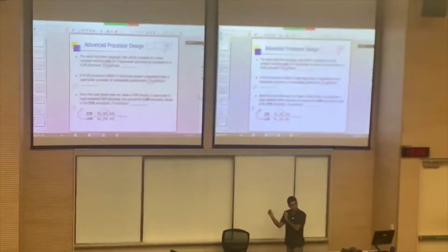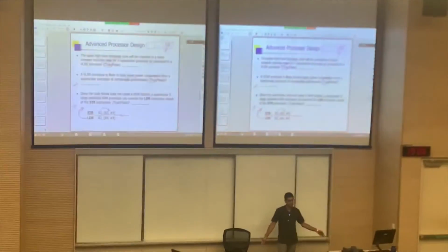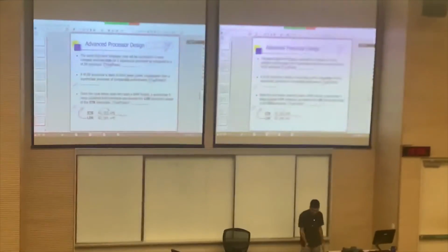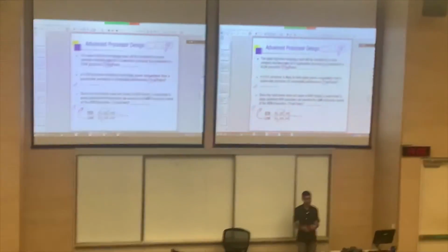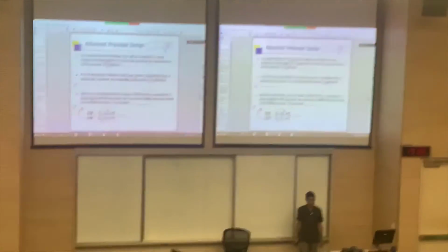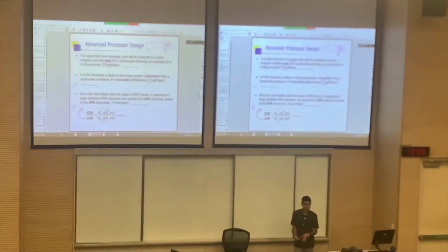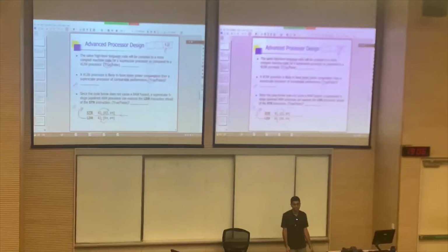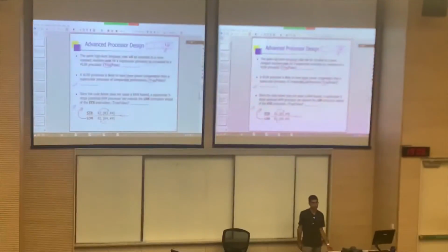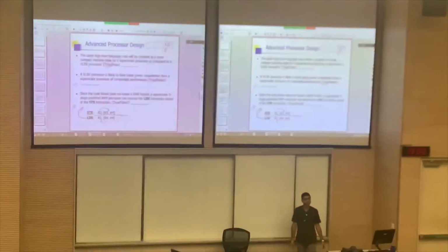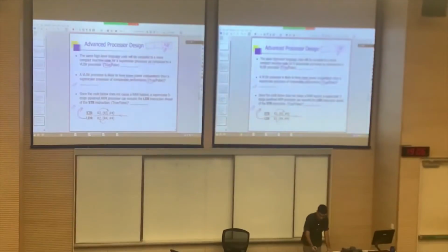Once that information is sent to the memory, you don't need the value in R2 anymore, and now I am just using R2 to store a fresh value. This is how we typically do assembly language programming, right? Once we realize that the value in a register is no longer required, we use the same register to store something else. That's why it manifests. This is a storage conflict, and it can be resolved through register renaming.